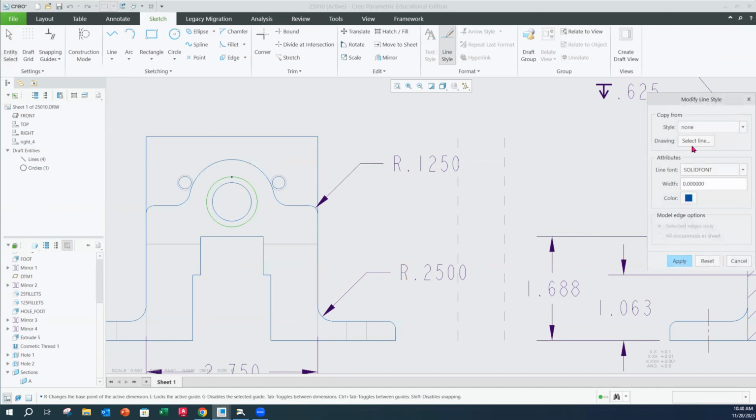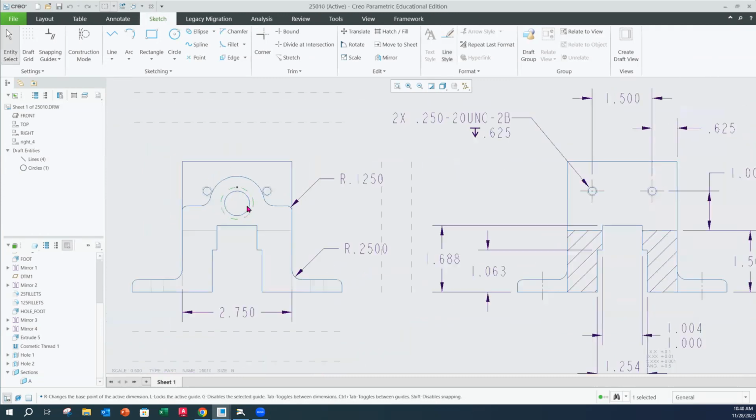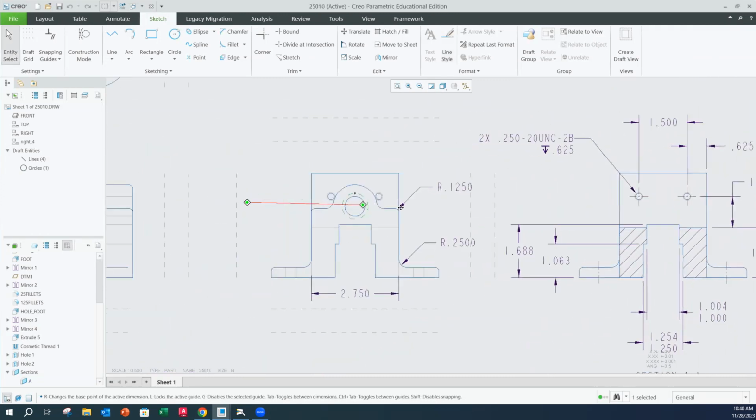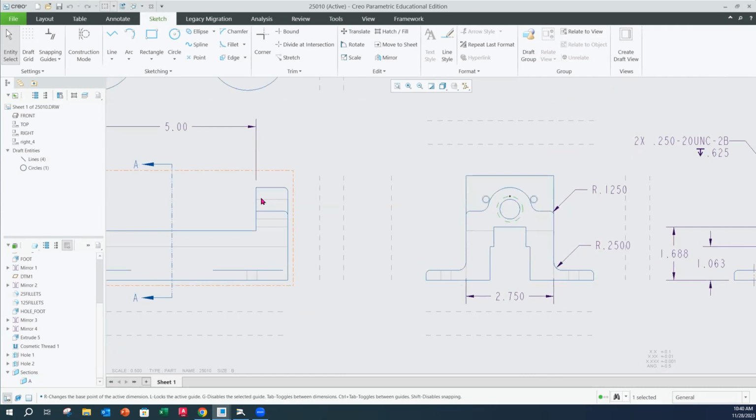We're going to click on that. We're going to go to a line style that is going to be a dash font. That's going to be a hidden line. Okay. So we're going to say okay, apply, and we can see a preview of it. That looks great. And then we're going to say close. And now it's there. All right. We can do that very same thing then for our side views to show that level.